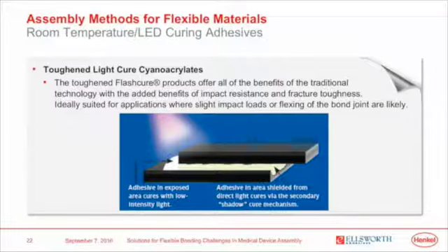Going on to another solution for flexible bonding, this is the first of the LED solutions that I'll talk about. This is a room temperature LED curing adhesive. It is a similar chemistry to the previous one in that it is a cyanoacrylate. However, in this case, it combines the benefits of a traditional cyanoacrylate, fast fixturing and curing, with the ability to cure exposed areas with light.